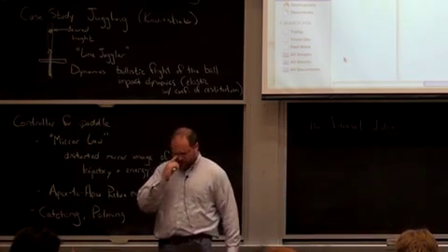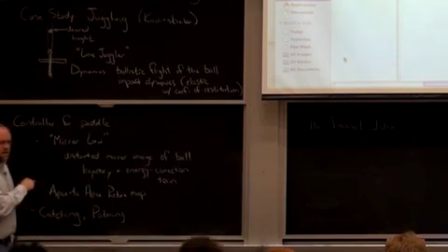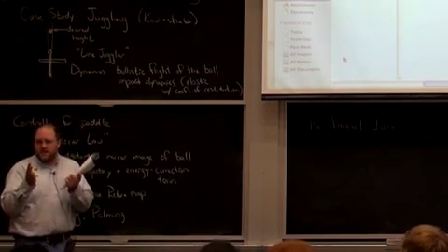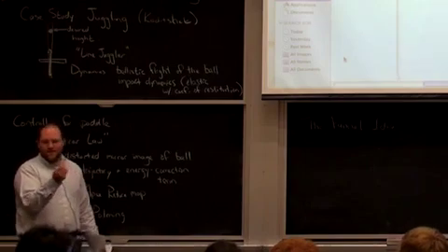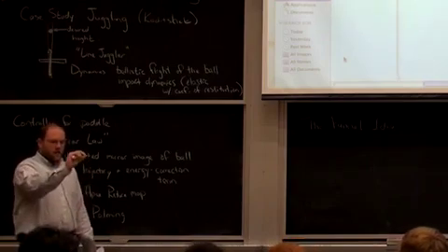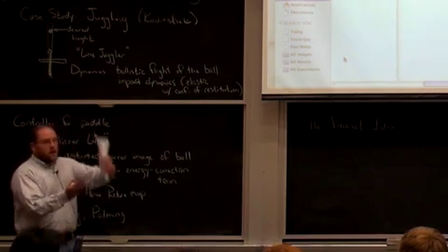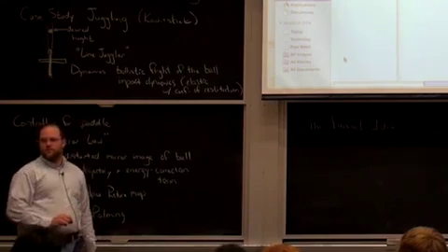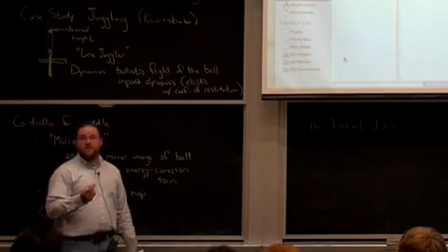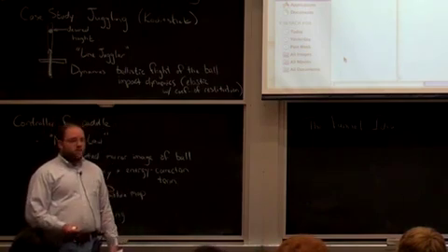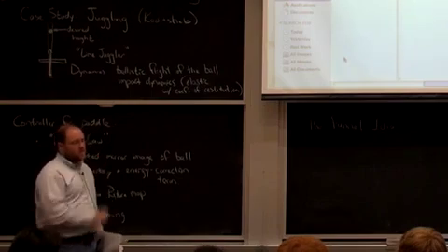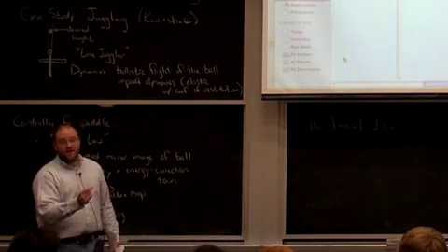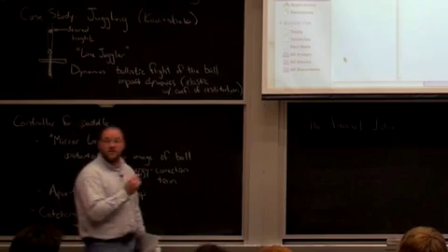Okay, so every one of those controllers had the property that it would take initial conditions in state space and move them to some more desirable state. So for instance, the ball hopping, the ball could be sort of anywhere here. By applying this controller for some finite amount of time, when it's done, it's going to be closer to its apex height. In many cases, not in the experimental juggling case, even in the model one, I guess they do, but in many cases you actually have Lyapunov functions which describe the way that convergence happens, okay, but it's not strictly necessary.